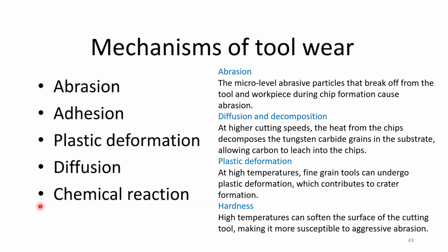Diffusion and decomposition. At high cutting speeds, the heat from the chips decomposes the tungsten carbide grains in the substrate, allowing carbon to leach into the chips.